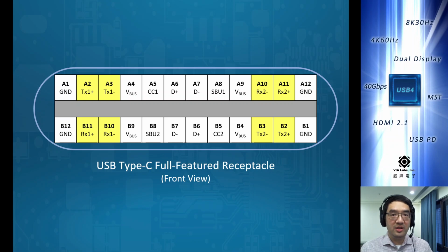And with the introduction of DisplayPort alternate mode on USB Type-C, we've taken the USB Type-C connector to carry both USB and DP. But the way we do it is we essentially take this one connector and split the wire pairs up so that we use half of it for USB transmit and receive, and then we use the other pair for DisplayPort for either 1 or 2 lanes.